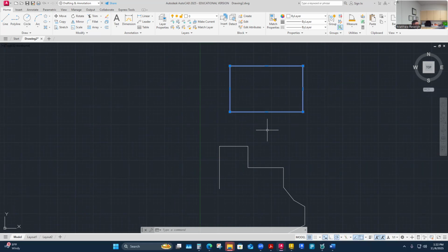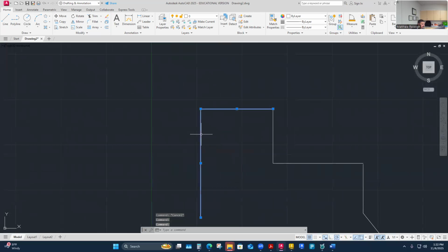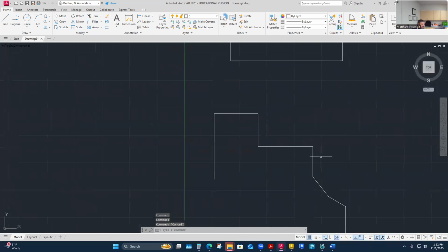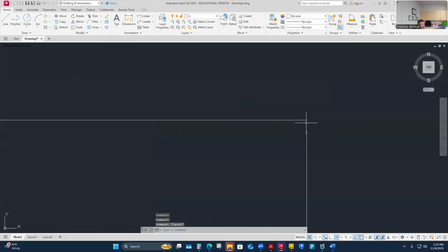The reason I show you this is because your machine, like your plasma, loves to cut things that are connected like this. It will cut stuff like this and you may think it's connected, but if you zoomed in on this particular part of mine where I wasn't connected, these are not connected. Machines don't like this. They won't cut there. When I drew this, I didn't connect the lines together. So the machine's going to cut that just like that.